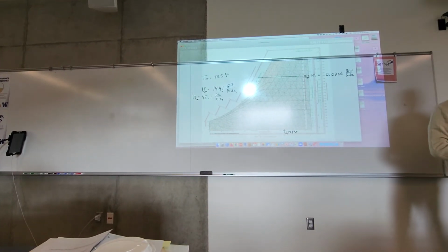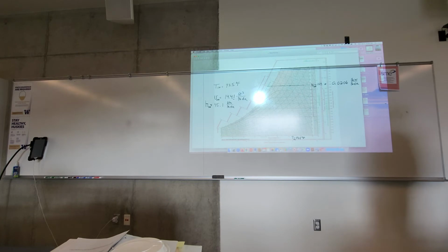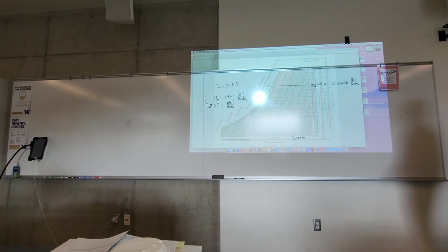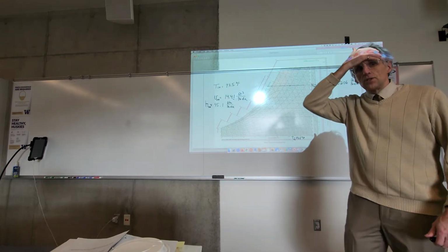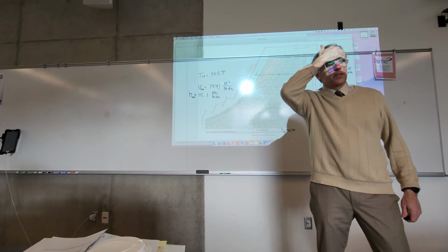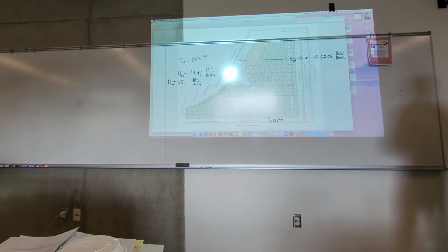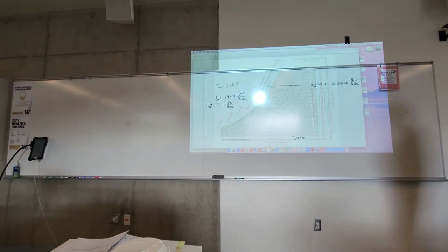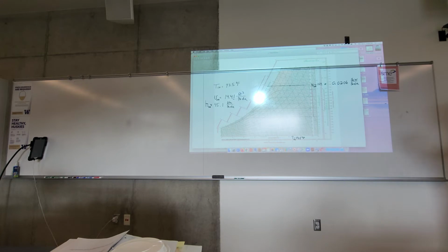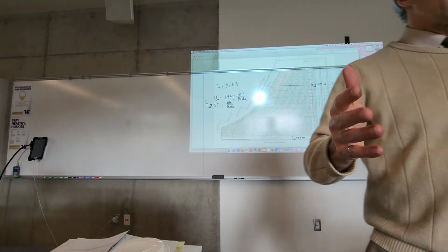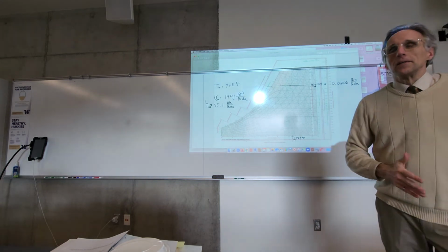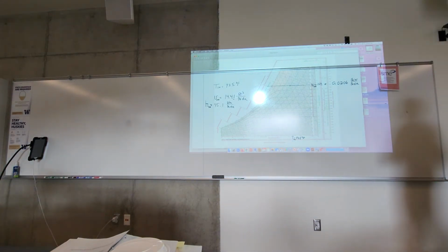And similarly on the heating side, when you're designing for cold, you would design for an almost coldest day. And I think in Seattle it's around 18 degrees or something, maybe low 20s, which is relatively mild compared to interior parts of the country where it can get really, really cold. So that's going to determine what the capacity of our system has to be. Then we just have to make sure we have a control system that can deliver less or more heating and cooling as needed given the outdoor conditions.